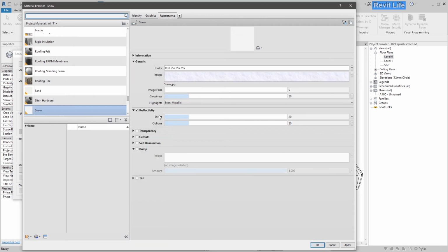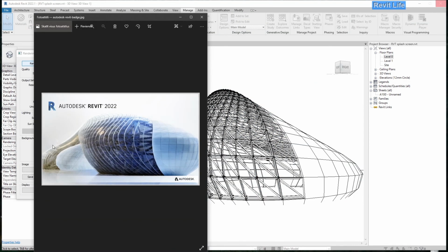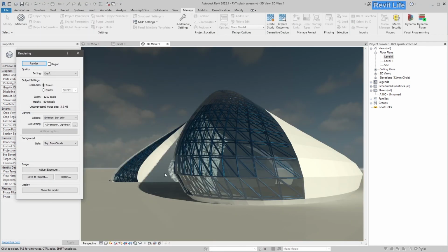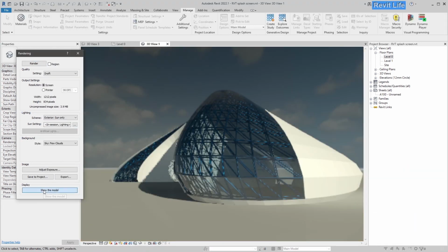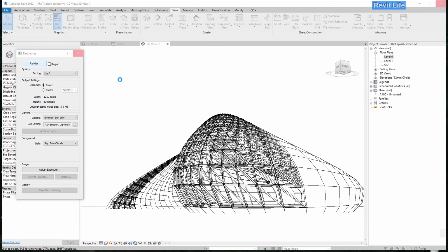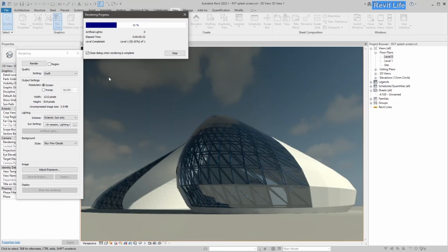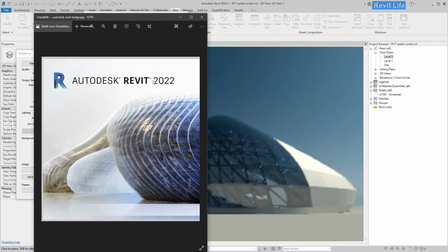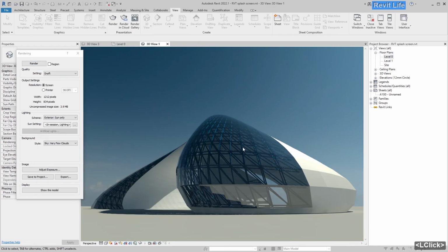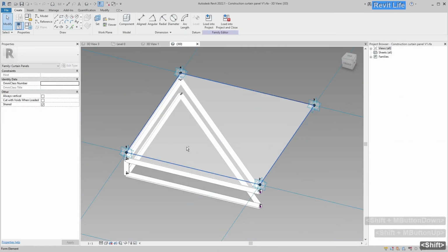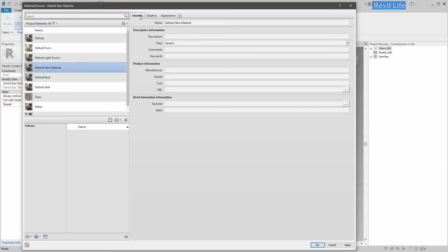And the problem with this was that when I try to change the material, let's say for the pipes, it takes way too long to recalculate the whole model. But for now, I'm trying to render the first images and to see what it looks like. Do I need to change the color of the materials, where the sun is shining from, and the angle of the camera, and how do I get the reflection in the glass. And next I noticed there is vertical ribs in the glass structure, and that is what I'm adding here, a material parameter to the side of the glass panel.